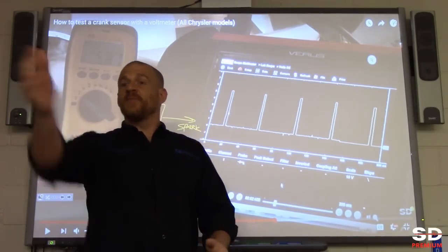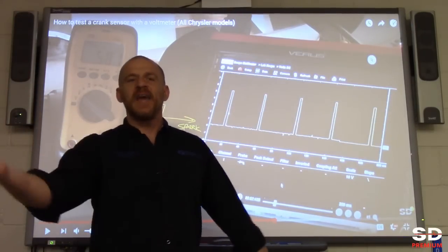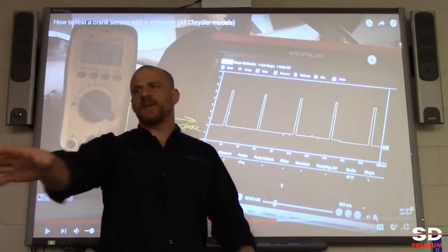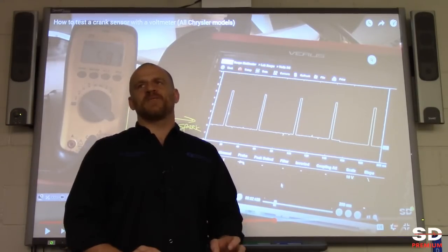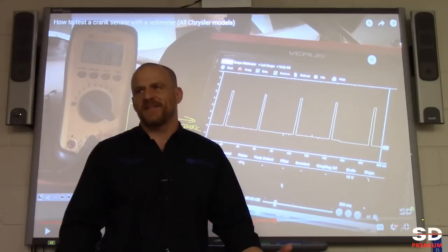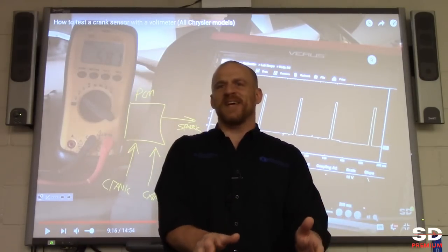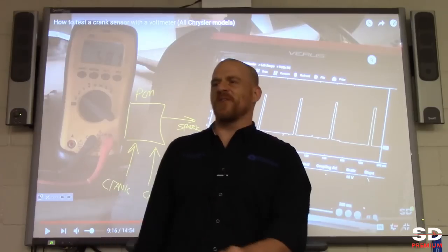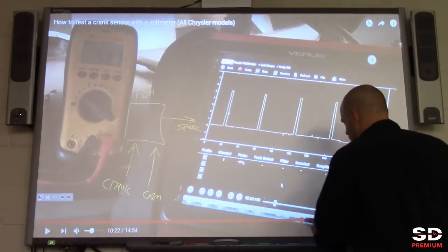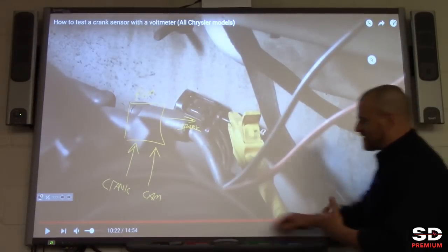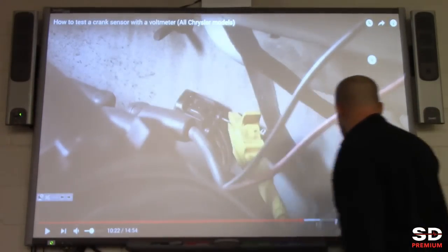I need the sync, and what I did to make the test work is I cranked it so I was providing the cam signal, and then I did the bypass and it worked. I admit this is probably not the best video to introduce the bypass test to you, because I'm teaching you something new, which is the bypass test, and then right away I'm throwing a variable at you with it. Sorry, I could have used a different one. Let's watch the bypass test, and then it'll be more clear, and I'll answer any questions you have.